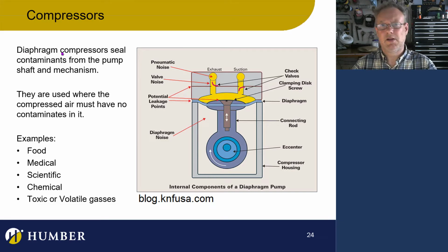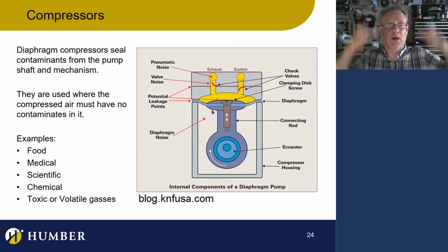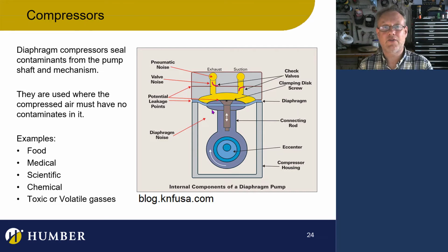Diaphragm. I hate it. I can't remember how to spell it. Okay, so there's a diaphragm compressor. What goes on there is there's no metal on metal, so we have a really clean gas. That's used in food, medical, scientific, chemical, toxic, or volatile gases.